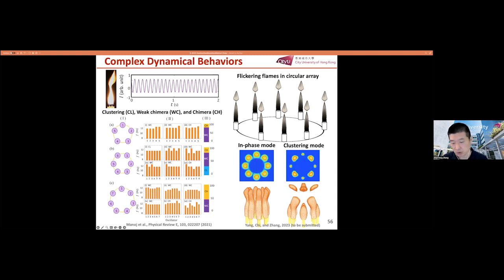It's close to, for example, turbulence is full of eddies with different time scales. Right? So if the time scale of the dynamic mode can be decoupled from those turbulent small eddies, just like when we do the LES, we do the filtering, right? So we filter those small eddies, small time scales. Then what we get is the collective behavior of those time scales close to each other. My approach is to provide a methodology to help us to extract some information like that.